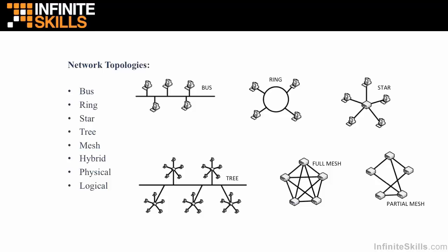As a node on the bus begins to transmit, the energy that is the signal, now this is electron flow pushed by voltage, we're pushing electrons, this electromagnetic energy, this electron flow, will propagate in both directions from that transmitting node on the bus. And if the energy hits the end of the cable and is not properly terminated or destroyed or absorbed, then the energy will reflect back into the cable and begin to destroy the oncoming signal.